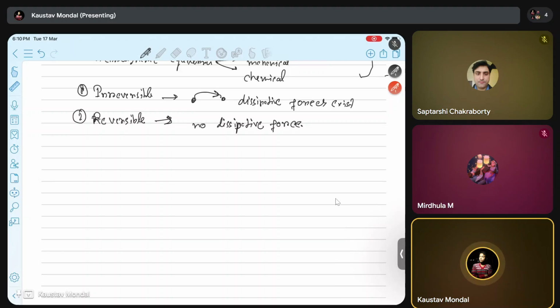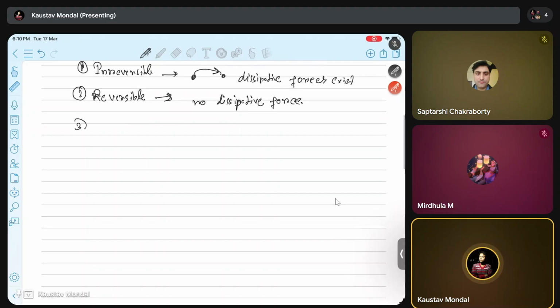The next thing that we have also discussed, also a very important process, is known as the quasi-static process. The importance of this quasi-static process is that in thermodynamics, this is basically a hypothetical concept where we change one of the variables or parameters of a thermodynamic system by a very small, infinitesimal amount, such that before and after the process the system basically retains its thermodynamic equilibrium.